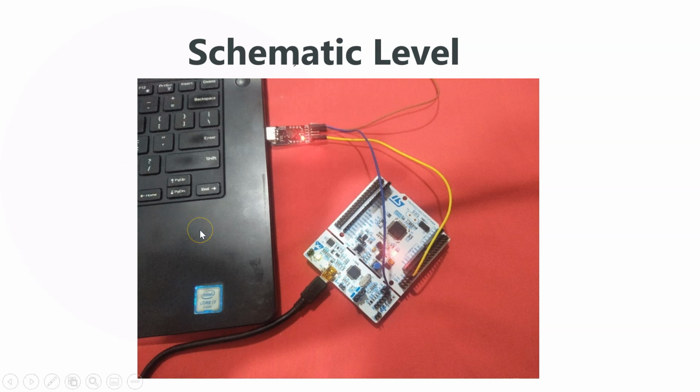Here this is the JTAG connection, which is again connected to your laptop. This actually is very useful. You have an ST-Link, which is the part used to program the microcontroller, and that's on board itself. You don't need an external programmer to program this microcontroller. So that's very handy in that sense. So that's the basic setup for your Nucleo board.